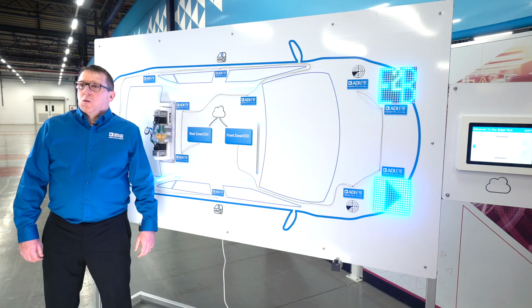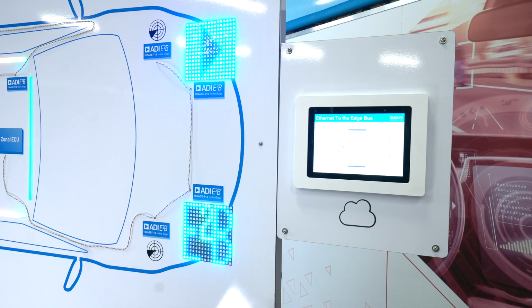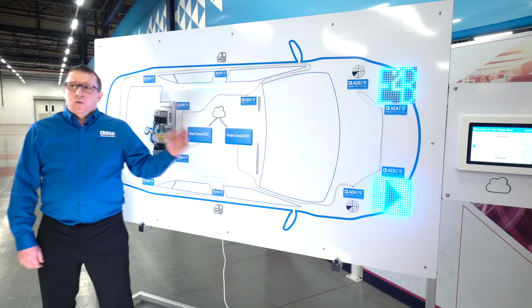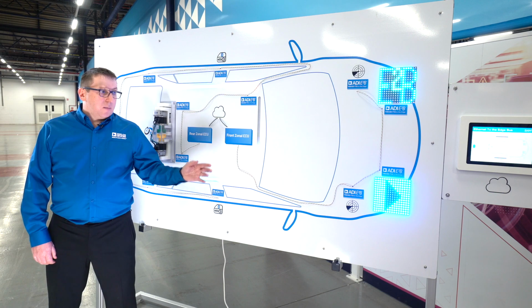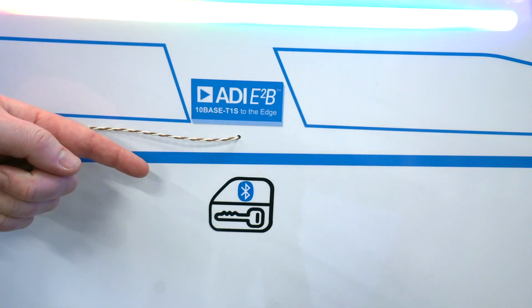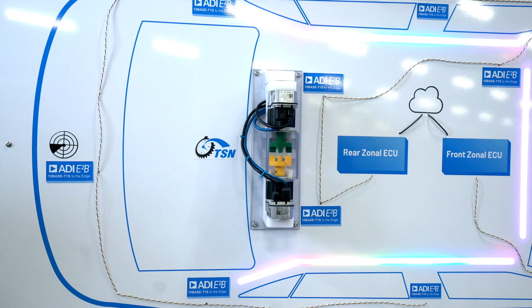Now let's look more closely at the hardware on our car model. The front zone with 4 E2B edge nodes consists of 2 radar devices measuring distance, 2 LED matrix panels for lighting applications. The rear zone with 8 E2B edge nodes consists of 2 BLE modules for keyless entry application, a radar module for presence detection, 3 LED strips for ambient lighting, and 2 motors.